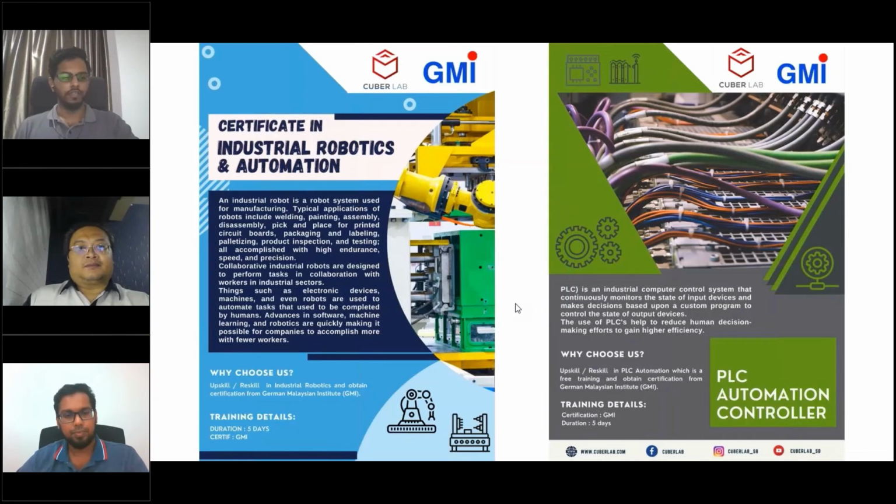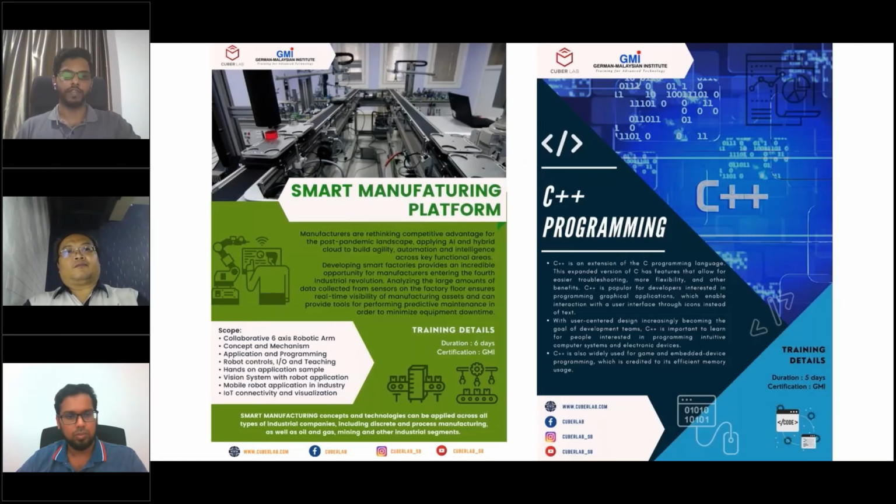Sure. Okay, vision system, there's a lot of types. We call it either vision sensor or vision system. Basically, we just teach the vision sensor to make a decision such as pass or fail according to color, shape detection, and size detection. It just gives a pass and fail only. Vision system is more advanced than that, and it has more tools inside it for object recognition, measurement, and tool orientation, all those things, and it gives data as output. So there are two types of vision.